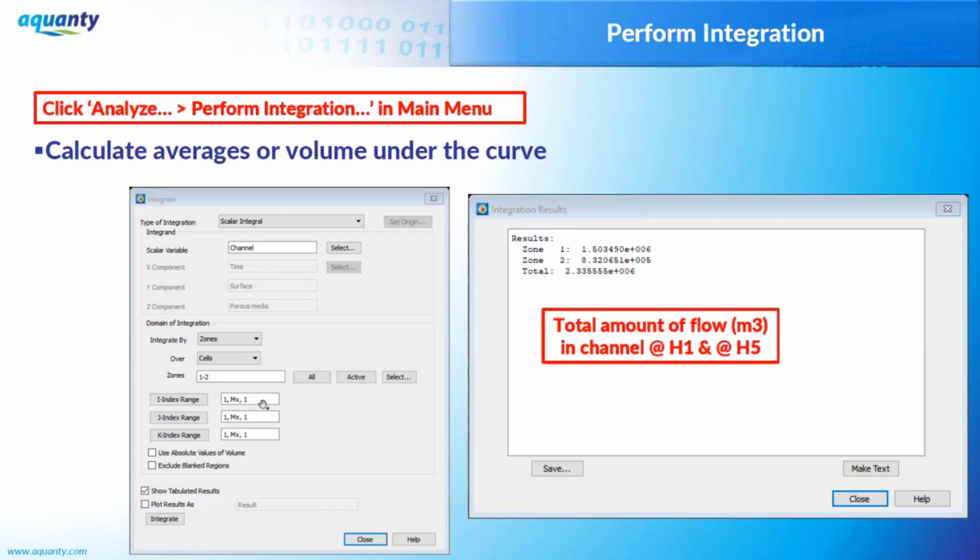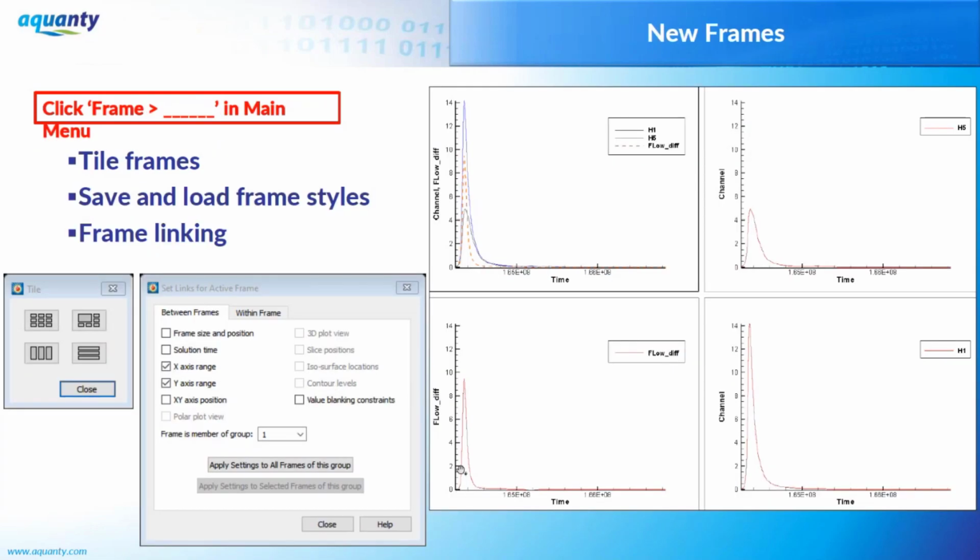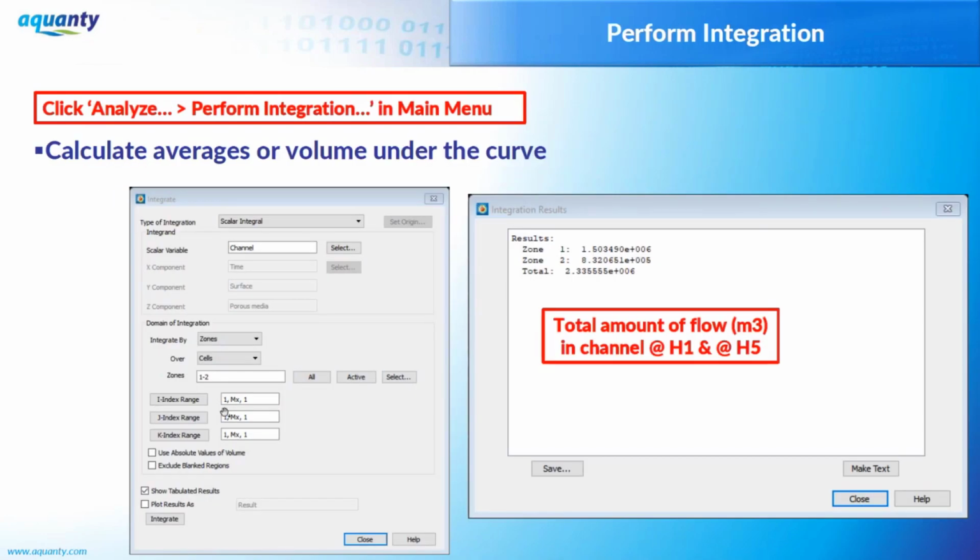In this case, let's say you have your hydrograph starting here, the rainfall event ends around here, but you get some tiny flow until it vanishes. But I want to look at the flooding period only. I want to look from 0 time, and I want to end it here. I want to only calculate for this part. In this case, I go to the index and I choose which index.